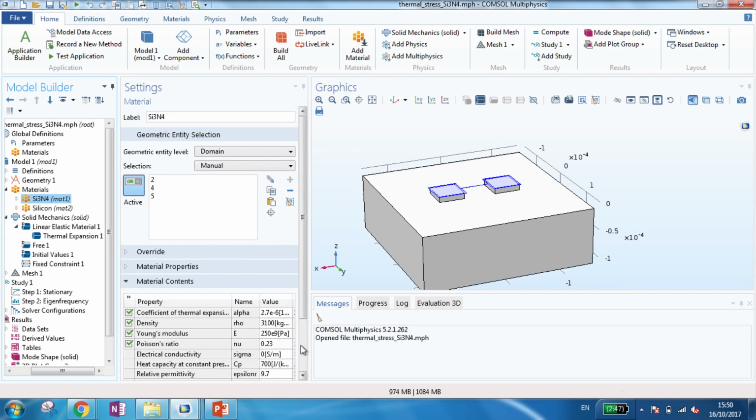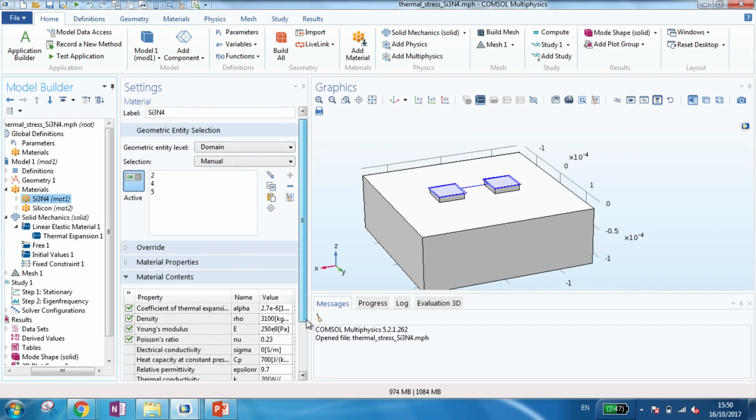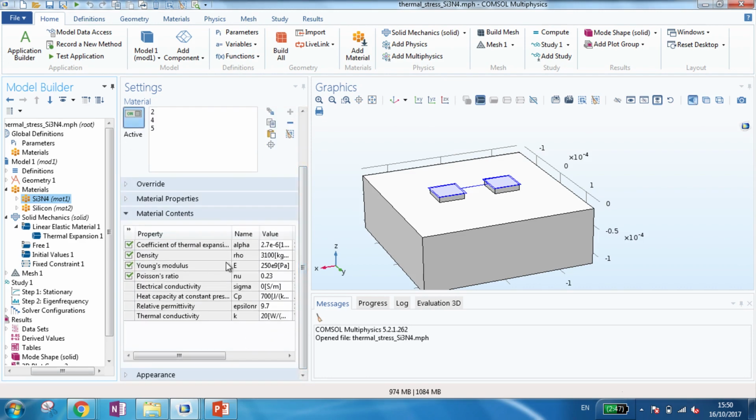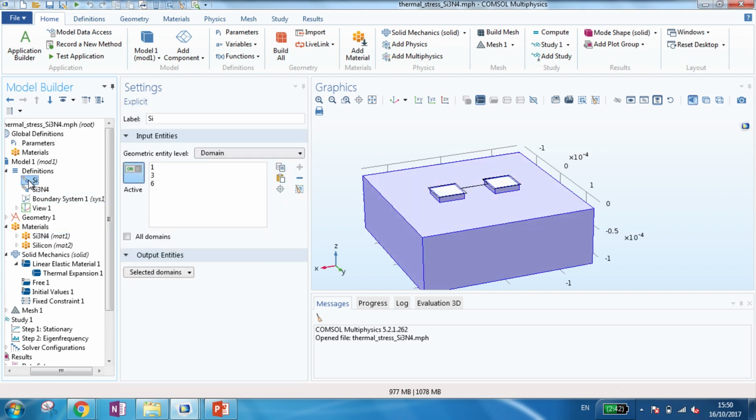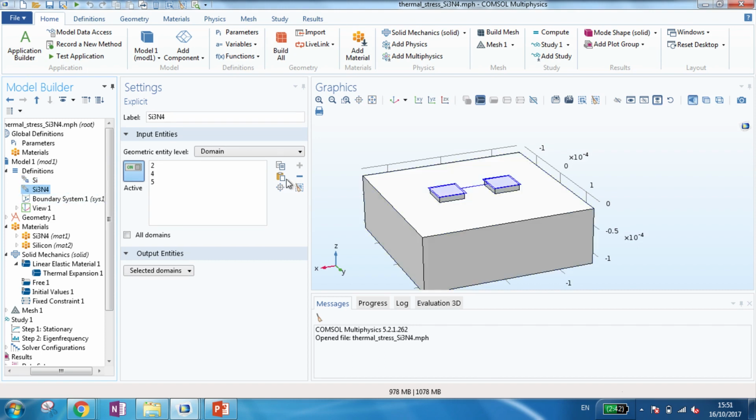And then again, fixed boundary conditions at a few points. And by doing that, we can do a pre-stress analysis, a stationary solution and eigenmode. So the stationary solution is going to basically relax this temperature, calculate how much expansion you get, and calculate the stress, and use that stress profile as the initial condition for this eigenmode solver. And if you do that, the result will be amazing.